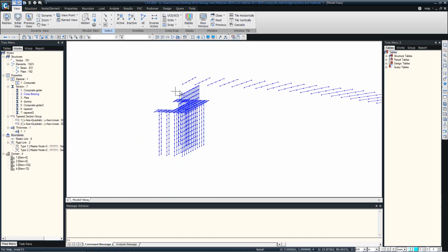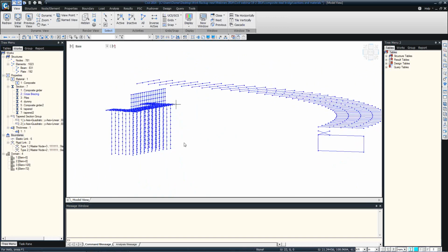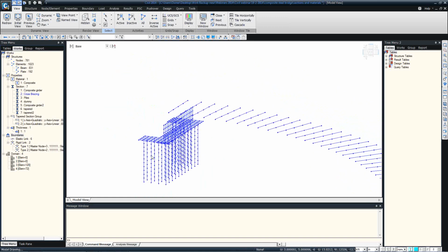So these are some of the important aspects of the curved bridge modeling. Now, just to finish up, let me touch up the precast infill type of section, which is a different section type because of the deck being poured in the spaces between the closely spaced precast beams.